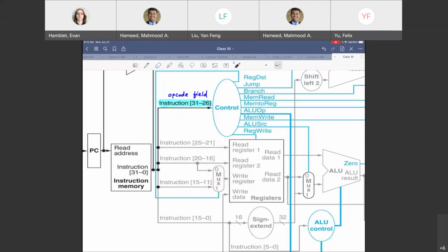Okay, give me an example. I'm writing to a register. Add I. Yes, add I will do it, right? Add I, that's an I-type instruction, and add I will do it because you have RS, RT, and the 16-bit immediate. You will add and then you will place it over there. So RT, that will work.